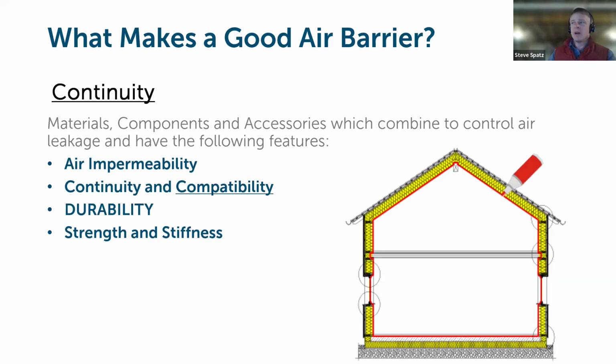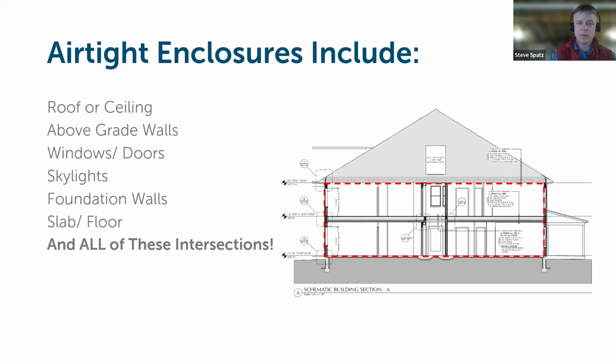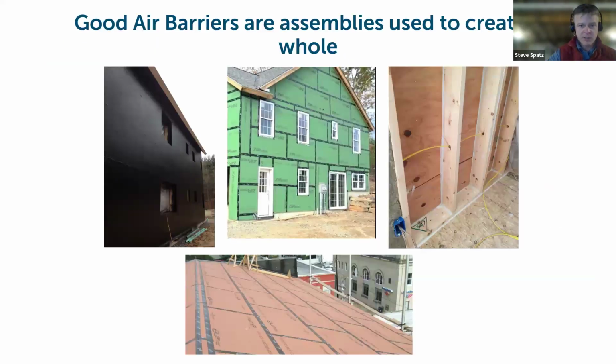Yeah, so with air barriers, there's continuity, compatibility, and durability that come into play. And this really goes for any of the control layers that we're talking about. Stitching together a bunch of disparate materials is oftentimes what constitutes the assemblies that we're talking about here. So understanding how to make those transitions occur between different components within the building, and then making sure that they're durable over time, is really what matters. So accounting for these as you can, before you start putting the structure together, into what your options and material choices are, and being able to delineate these on construction drawings, if and when possible, is always ideal. And then once you start to put them into practice, understanding what your options are for controlling those outcomes.